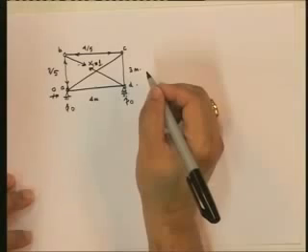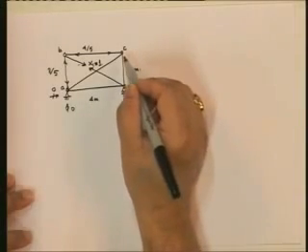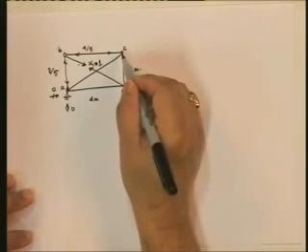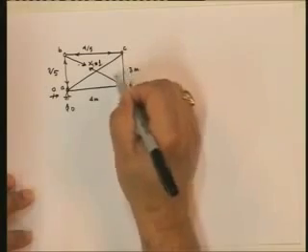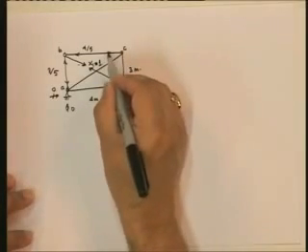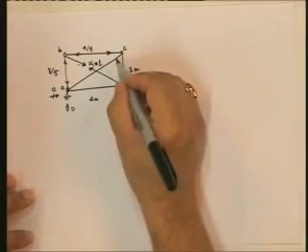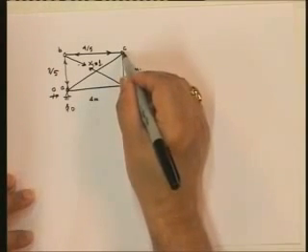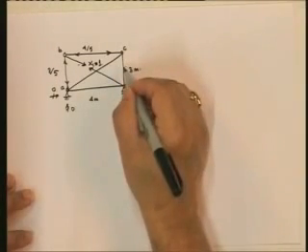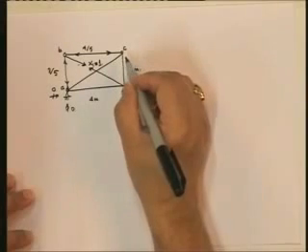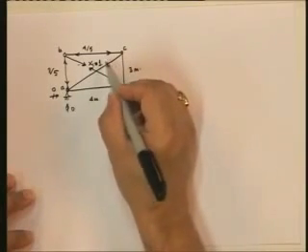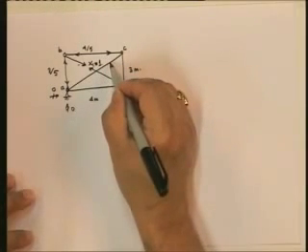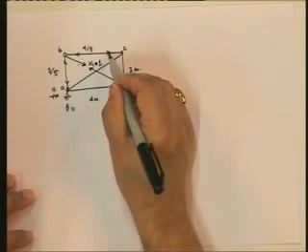And now let's look at the other force. Let's look at this. If you look at this particular situation, okay, what's the force? I know this force. What are the two unknowns? I don't know the force in this member and this member. Well, sigma fx equal to 0 and sigma fy equal to 0 will give me. What will sigma fx equal to 0 give me? That the force in this member, the horizontal component of this plus this is going to be equal to 0.